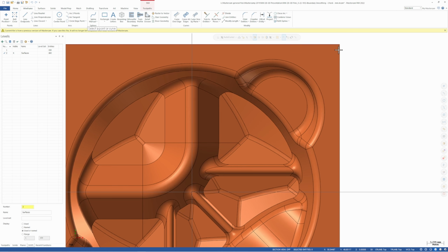It's not detecting any points. Now, the way around that normally, if you already know, is to create wireframe. So you have in the wireframe menu a section called create curves, all about creating wireframe geometry on surface models. However, sometimes you just want to do a quick bit of endpoint selection or endpoint snapping on a surface without having to draw a wireframe. The ability is there if you know where to look.